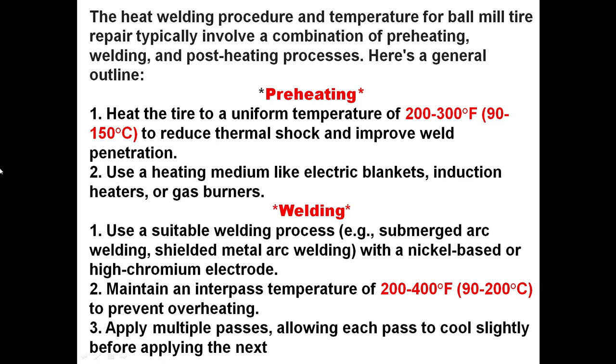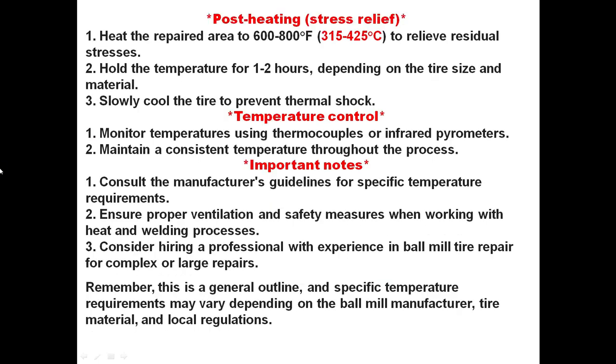Apply multiple passes, allowing each pass to cool slightly before applying the next. Post-heating: heat the repaired area to 300 to 425 degrees to relieve residual stresses. Hold the temperature for 1 to 2 hours, depending on the tire size and material. Slowly cool the tire to prevent thermal shock.